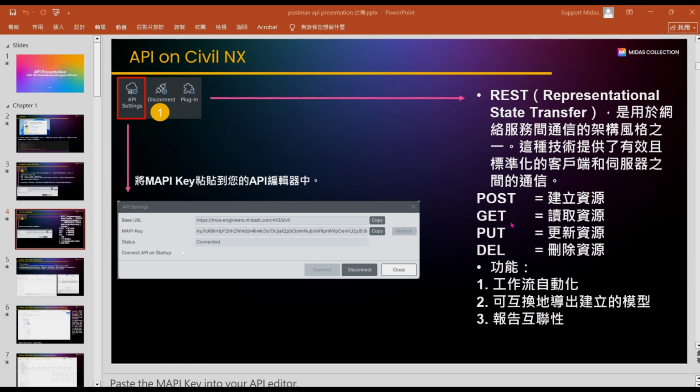And then for get is, for example, if you have a model, with a lot of complicated nodes, complicated section properties, complicated elastic link, complicated rigid link, for example, you can use get to obtain the script for that particular section. So if you want to see the script of section properties, for example, or the script of construction stage load, for example, you can use the code.